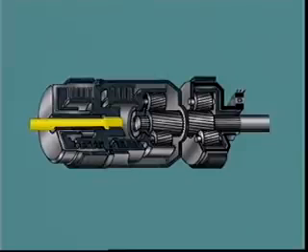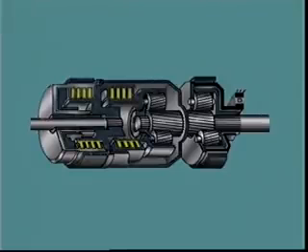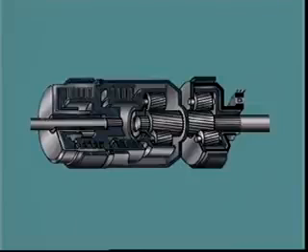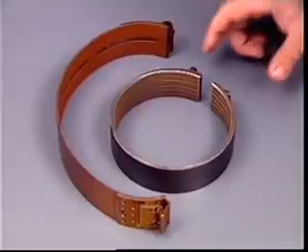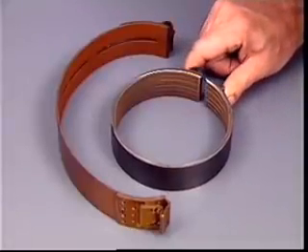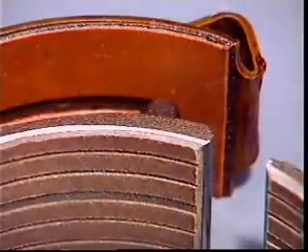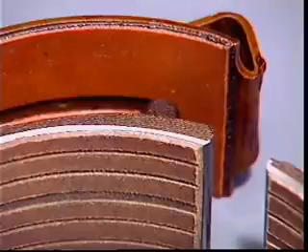The input shaft is separate from the gear set. The drive is transmitted through one or more clutches, depending on the gear and range engaged. Two bands and a one-way clutch are also used to control the gear set components. All bands are externally contracting types and have a thin layer of plain or grooved friction material bonded onto a spring steel or cast steel backing.